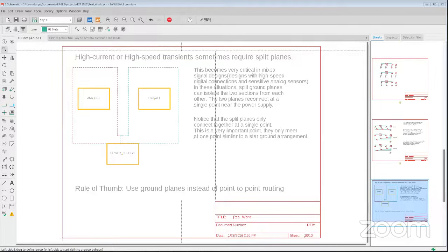Because by default, if you have a pair, the meander is going to look at the larger of the two and set that as the length to match to. However, if you're doing a single net, what it'll show you is just the measurement of the net, and then if you input a length that's greater, it will add meanders.